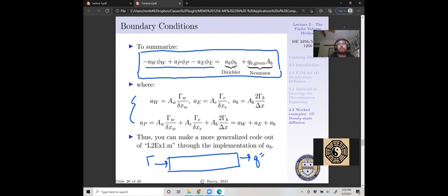When we're specifying this equation, I should mention that it's only at one control volume. That is to say, our problem would be ill-posed if we specified both the flux and a temperature here, because that would provide two boundary conditions for our second order differential equation. And then if we specified anything on this end, it'd now be an overspecified problem.